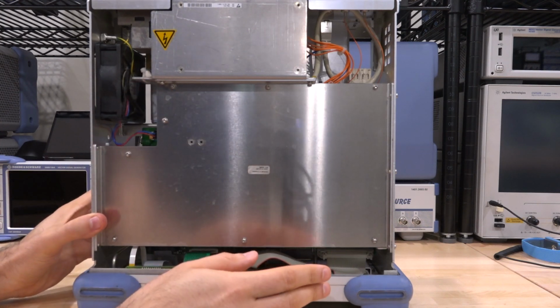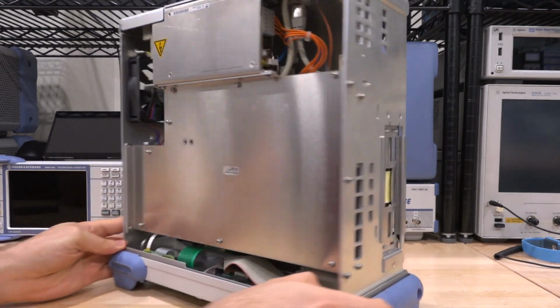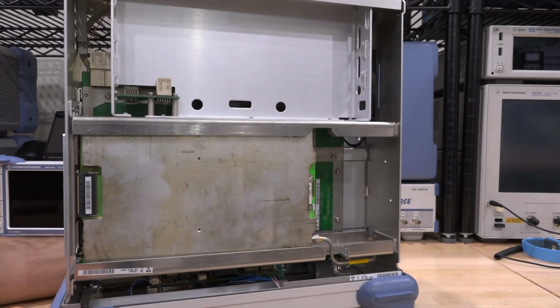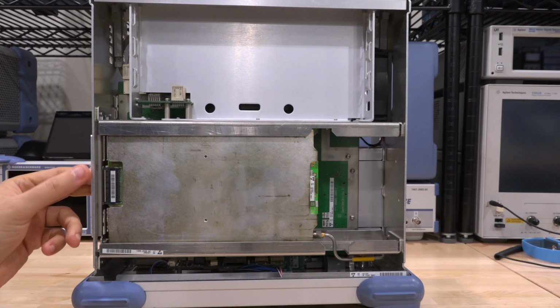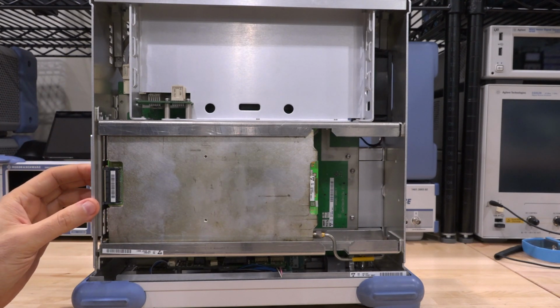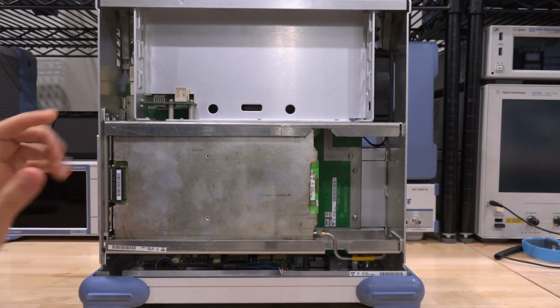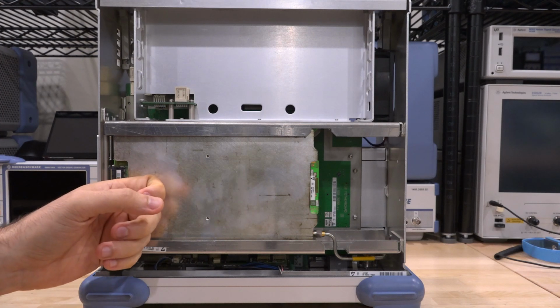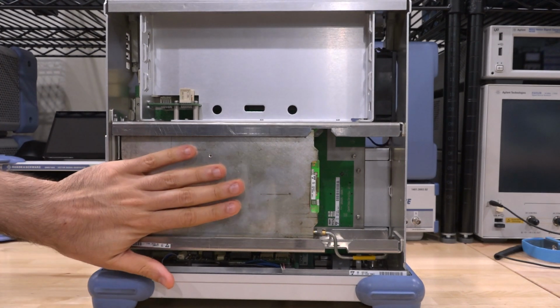A power supply up here, nothing really unusual aside from that. So we really need to pay attention to this guy. Now, the ribbon cable over here is far too thin to carry anything more than potentially a 10 megahertz signal, maybe a 100 megahertz signal to some bus somewhere else, but I would imagine that the digitizer is in here. So this is carrying the digitized information of the spectrum. So we'll find out when we take it apart.